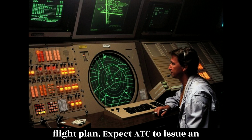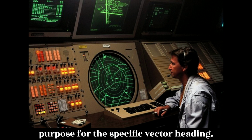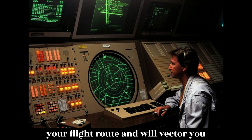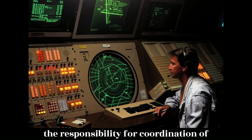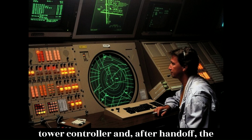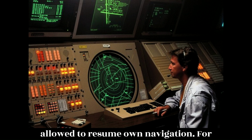Expect ATC to issue an initial departure heading if you are being radar vectored after takeoff. However, do not expect to be given a purpose for the specific vector heading. Rest assured that the controller knows your flight route and will vector you into position. By nature of the departure type, once you are issued your clearance, the responsibility for coordination of your flight rests with ATC, including the tower controller and, after handoff, the departure controller, who will remain with you until you are released on course and allowed to resume own navigation.